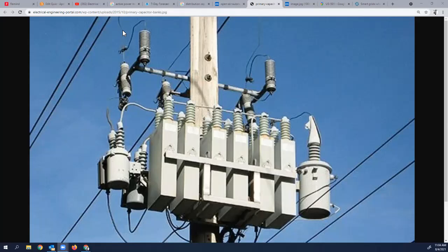You're still in really close proximity to these phases, so I would maintain my hotline work permit. Got all 3 risers on. Now that I've completed that, I can back away. I'm away from my feeder primary. I'm going to use a regular switch stick. That's when I'm going to cancel my hotline work permit and close the switches with my switch stick.